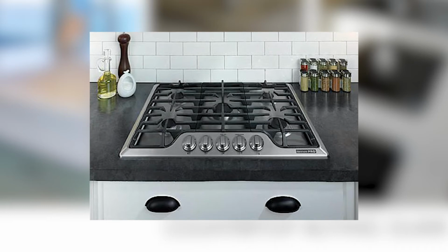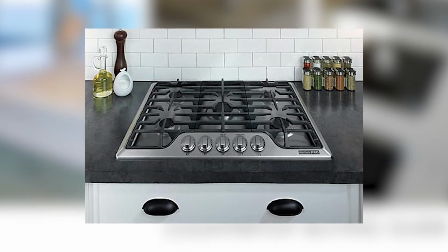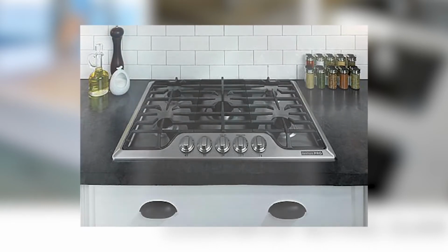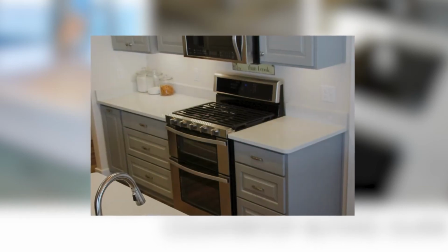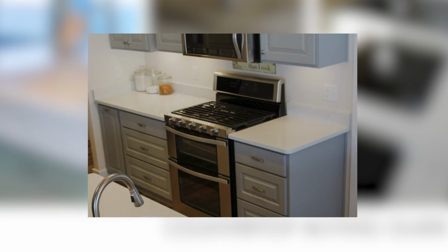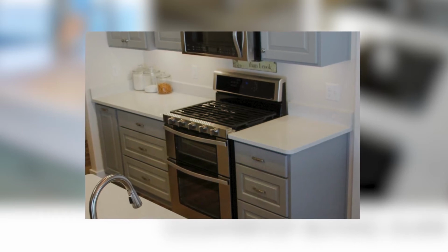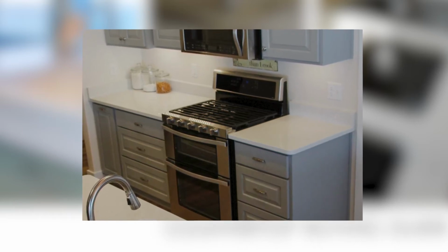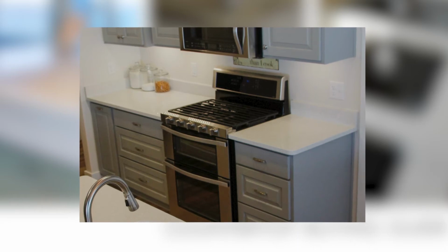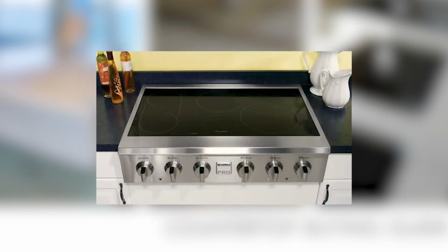Drop-in cooktops will need to be on-site at the time of templating. They will be dry fit during installation. Failure to have cooktops on-site will result in delays and additional trip charges. The most common style of ranges are freestanding ranges, which have the controls on the back. They generally require a 30-inch opening, and the sides are polished. These ranges are not required to be on-site.